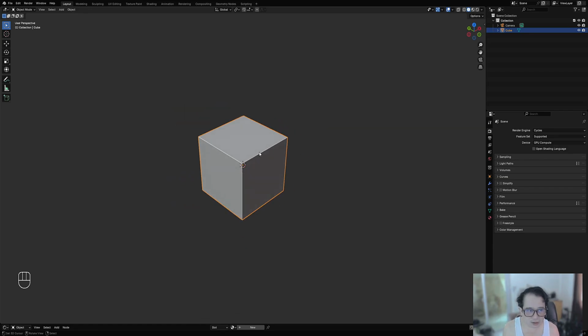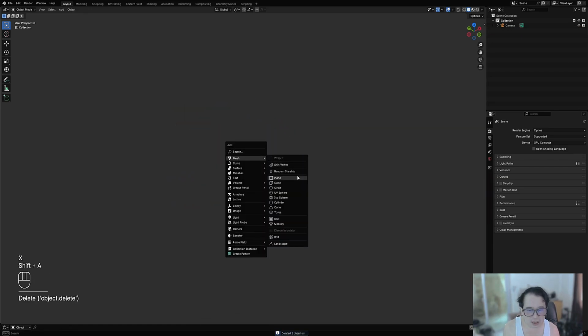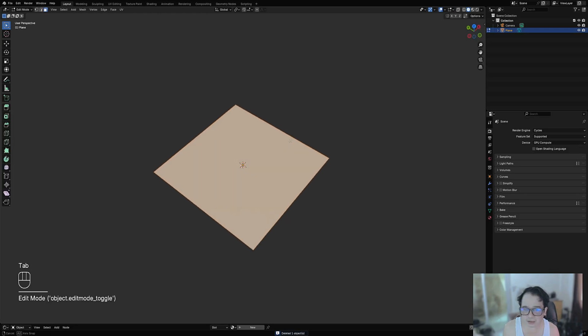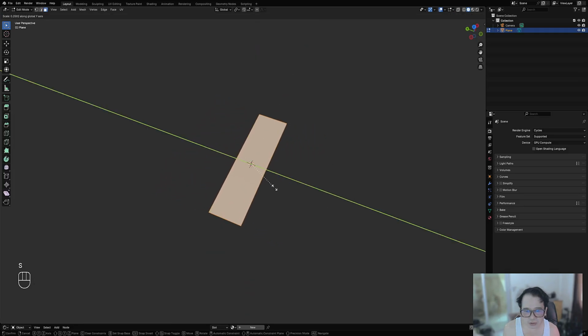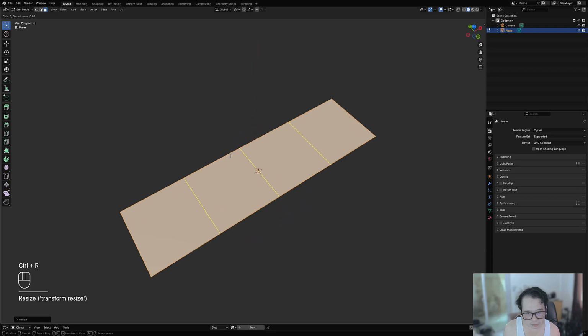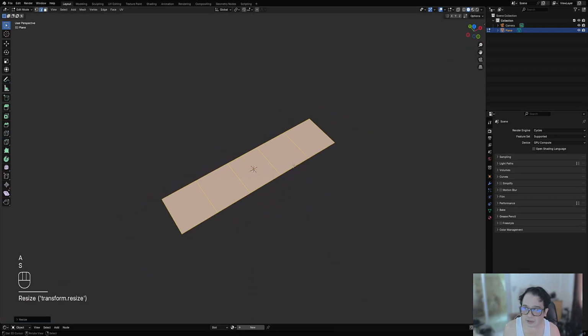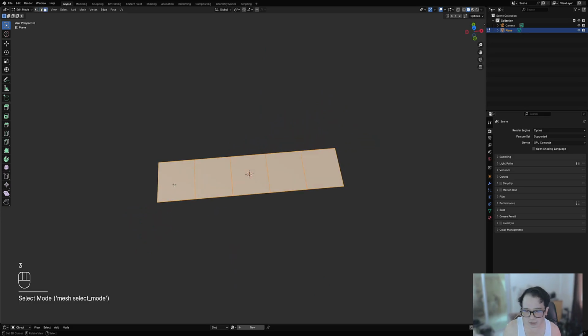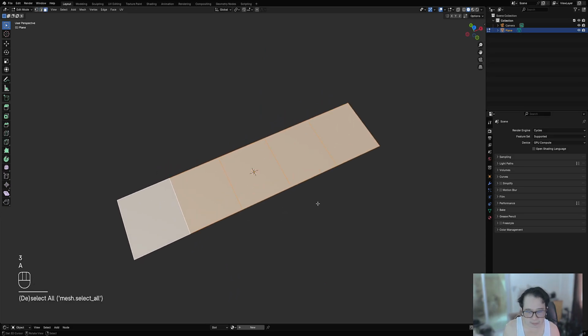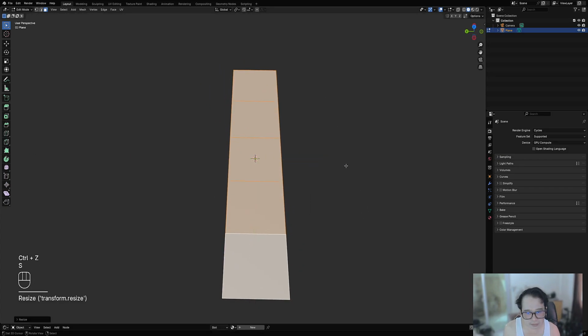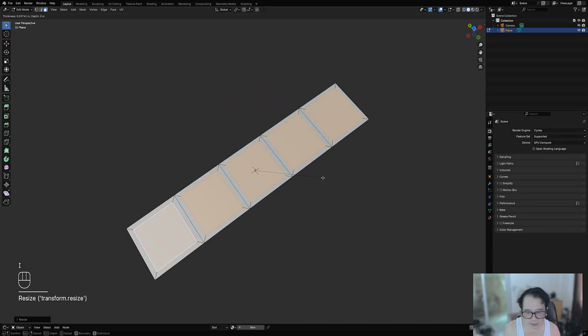Okay, so to start with, to save up on time I'm just going to use probably 5 iterations. You can use a plane for this and just use more squares. But for this one, inset and then press I again. So I for inset, then press I again to activate individual insetting. Actually, make this a bit more square.